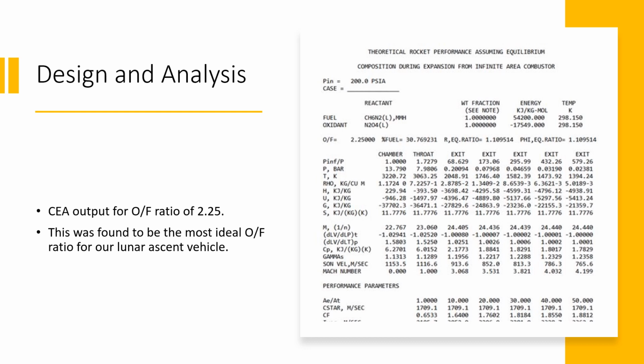Using NASA's chemical equilibrium analysis, various combinations of fuel and oxidizer can be tested to look at their effect on specific impulse. For a rocket problem such as this, the chamber pressure was set to 13.79 bar. The fuel and oxidizers were set to MMH and dinitrogen tetroxide. Various oxidizer to fuel ratios and exit ratios were tested to determine the best potential configuration.